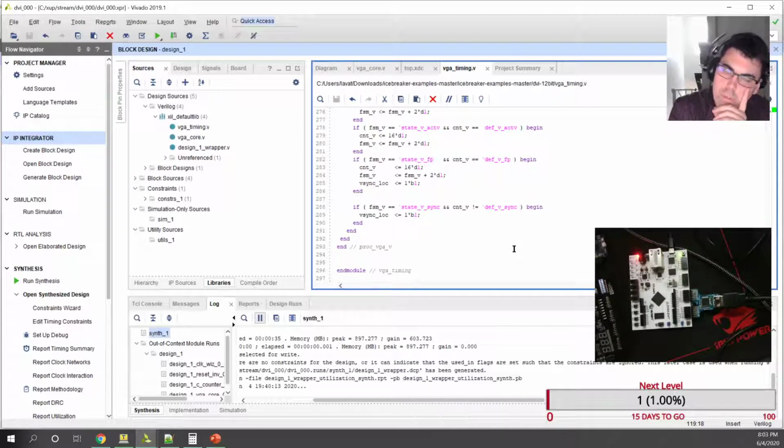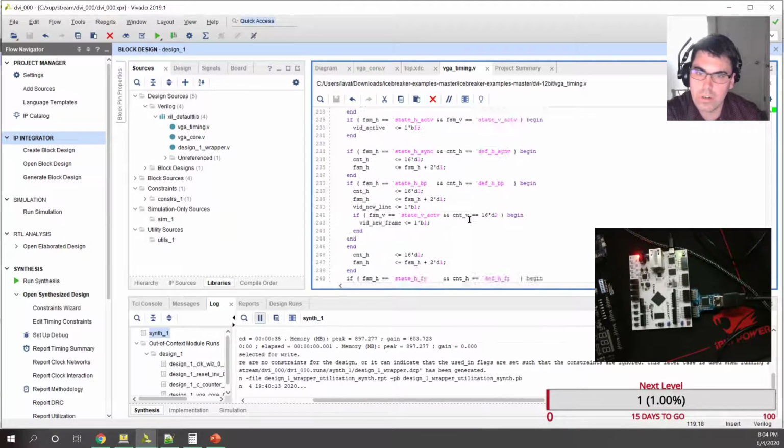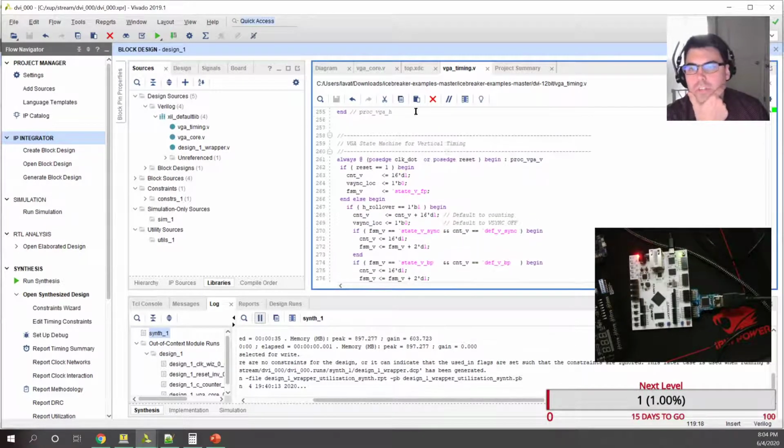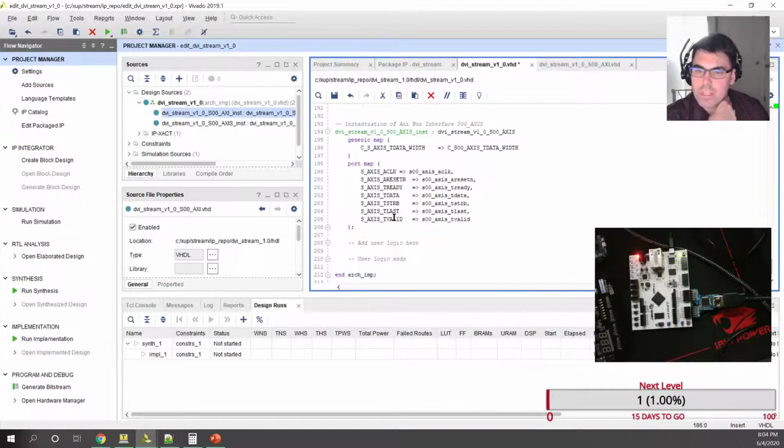We assume the data is going to be already correct, and that the active, and then we could probably delay them a little bit, get some stuff going, and double register on the output just for good measure. Do a fall through. Okay, yeah, we can do stuff like that. Do a small asynchronous FIFO. We could potentially change the clock domain. Now let's just do a clock. We'll just do an asynchronous FIFO at this stage.